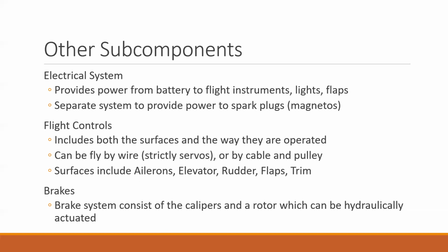So they're pretty simple. In case you're curious, hydraulic fluid on an aircraft is red. So if you ever walk by an aircraft and there is red fluid underneath the landing gear, you might want to take a second look at that, because there's usually a problem with the brake lines. So you never want to see red fluid underneath an aircraft.